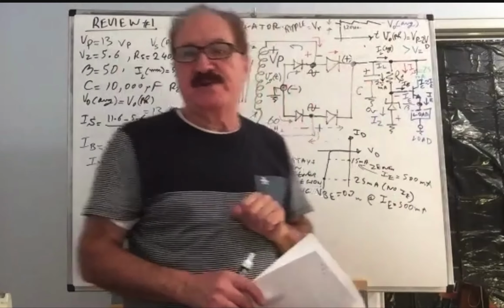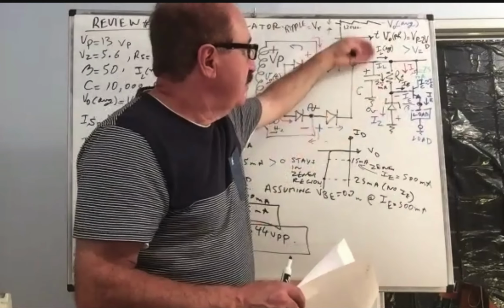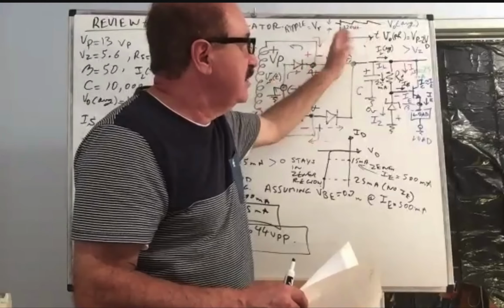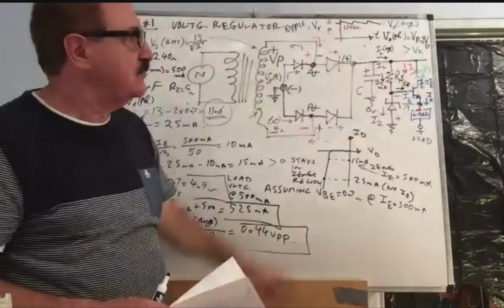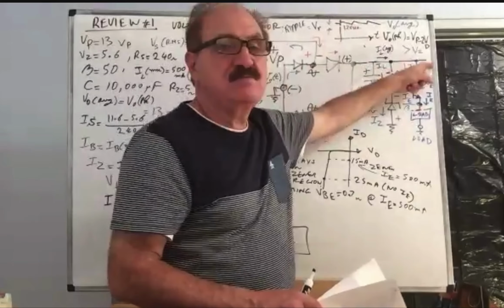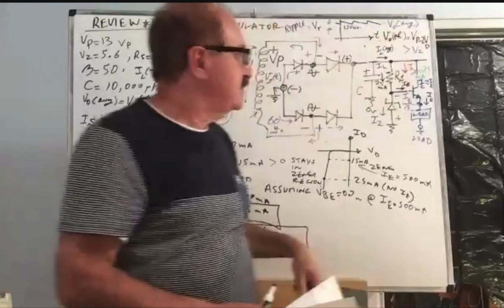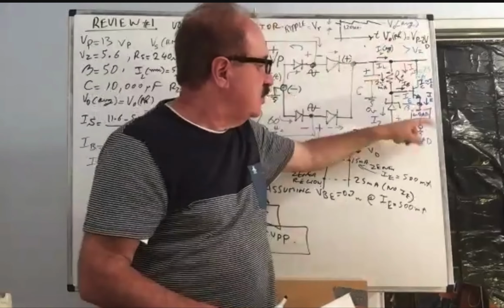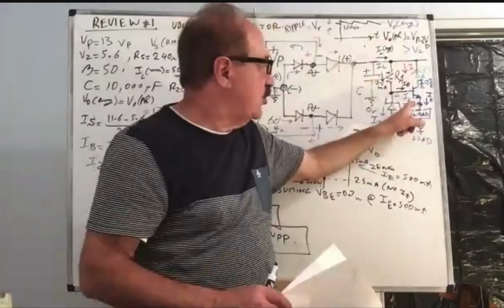That's the whole point. So that 3.8% ripple will be stopped because of that transistor stage. The collector voltage can drop, but it will not influence the collector current. The collector current is what you are drawing from the emitter, what your load is drawing at the emitter.